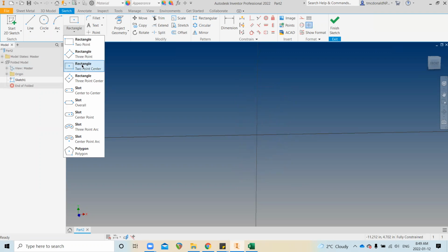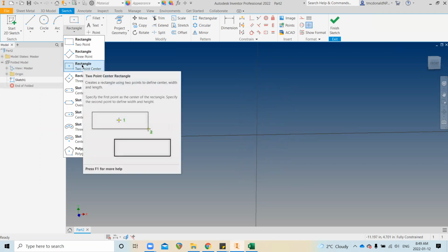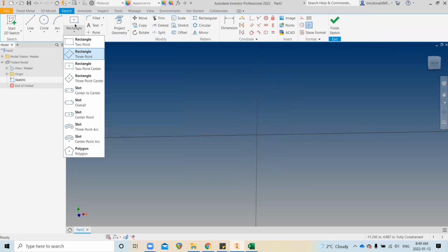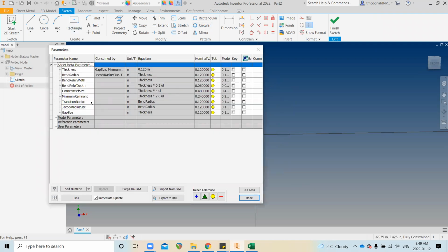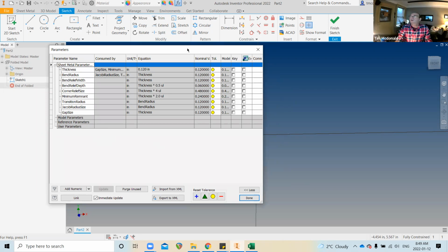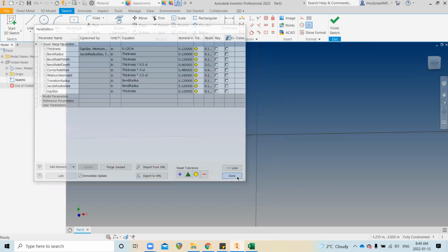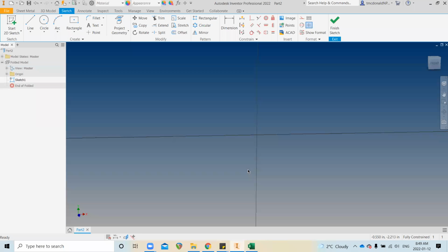Professor, yes. I think you deleted the entity with the window. You have already deleted that origin. There is a predefined origin. So that's why it's not constraining properly. You have created a window and deleted the whole entities. So the origin was there. It was also deleted now.